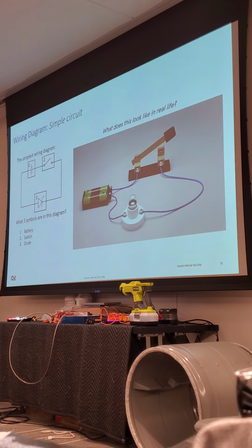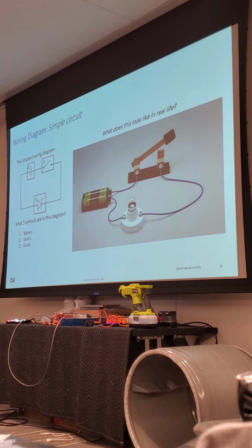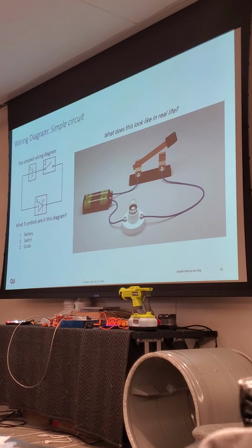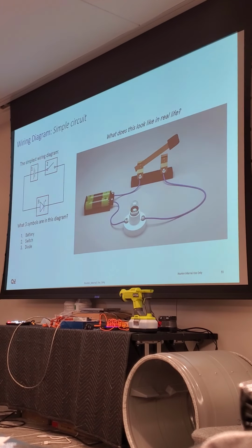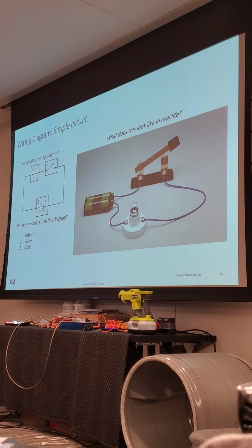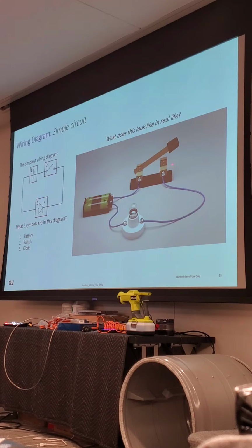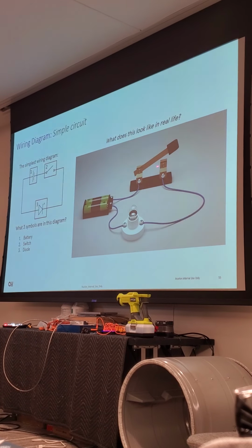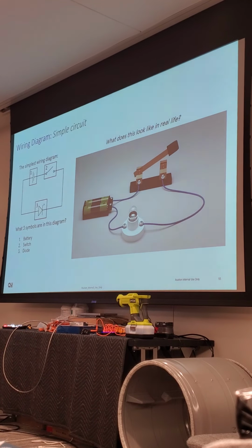Isn't that what the arrow means? It's a light activity. Yeah, that's also giving you a direction of the path. So it's coming from the plus side of the battery through the diode to the switch. To complete that, they've got to close the negative side of that switch so that it gets a full path.